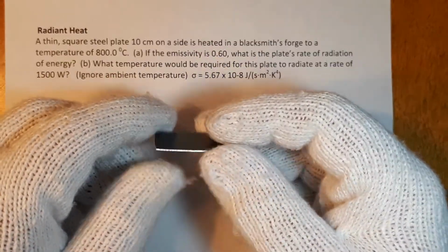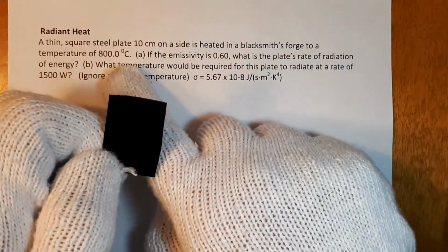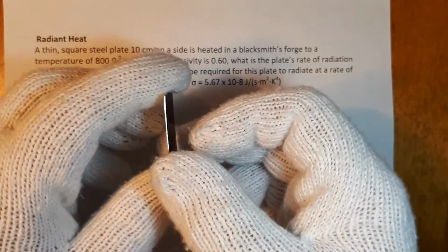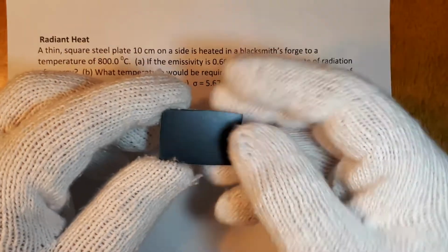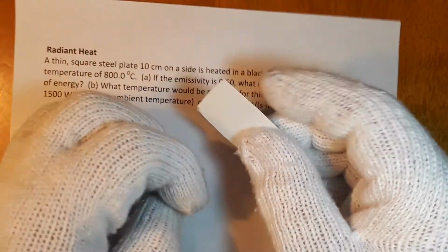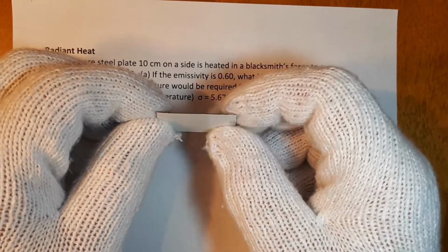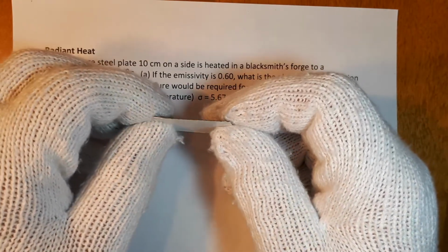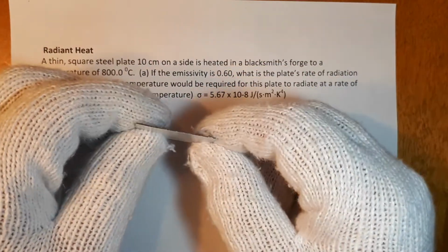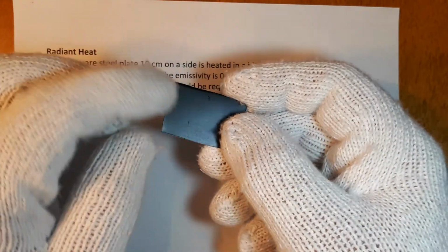Ignore the color, it really has nothing to do with this particular word problem. If it gets heated in a forge at 800 degrees Celsius, when I take it out of the forge, it's going to radiate heat back into the atmosphere. But it will radiate heat along this surface into the atmosphere, as well as the backside into the atmosphere. It will also radiate some heat through the thickness of the material, but the thickness in this case right here is, well, negligible. So in our word problem, we're going to ignore the thickness, any heat being radiated back into the atmosphere from the thickness, and only concern ourselves with this surface area and the backside.